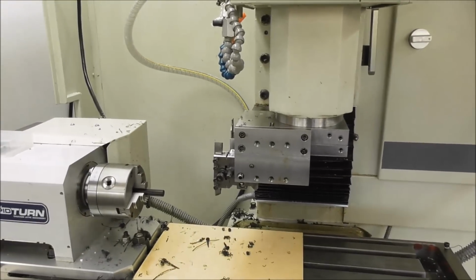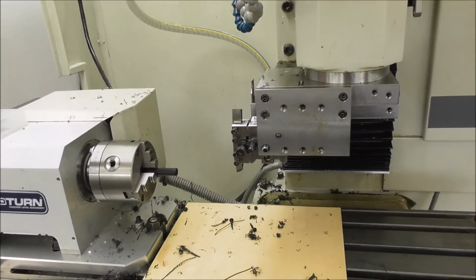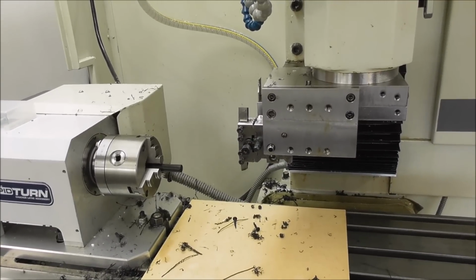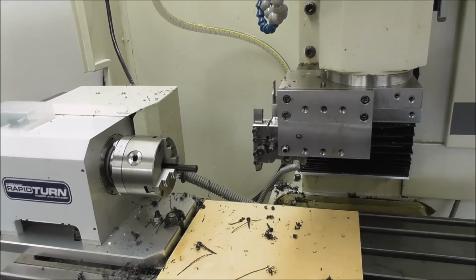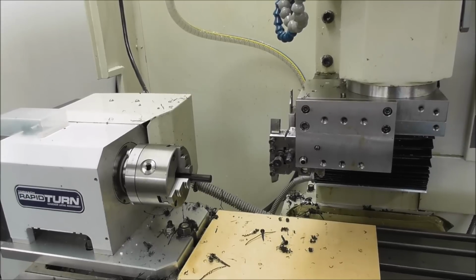And that way we've checked the tool path in fresh air well away from the chuck. And we could do that in the Z, which is the longitudinal, or in the X, which is up above the chuck, or in whatever position where you think there's a big block of fresh air and you can run the tool path safely.